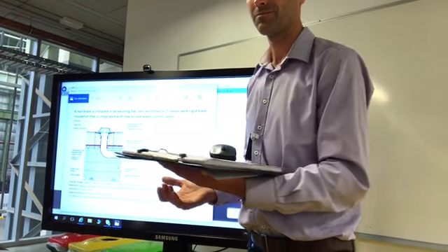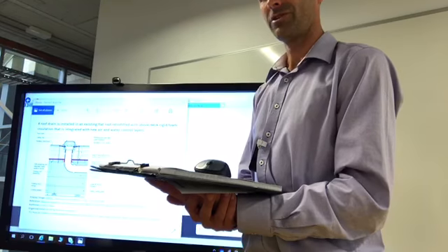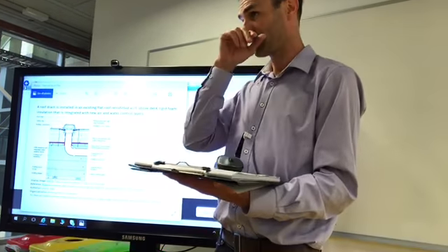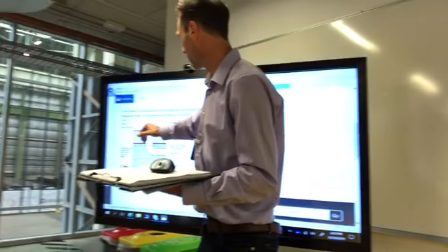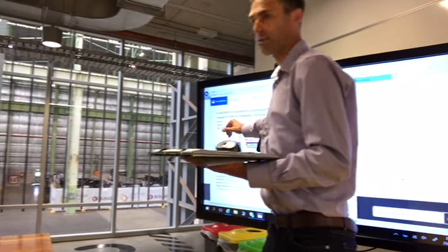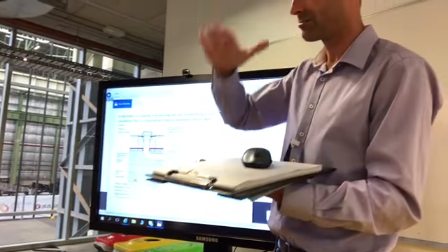So what did you put on there in that case? Don't know. Haven't dealt with that. If it's going to be trafficable for a green roof, well then we'll have a depth of this aggregate here to provide drainage, and then we have a drainage medium on top of that.